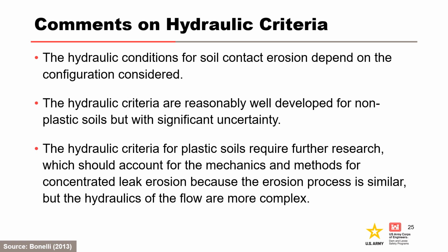So as seen on the previous slide, the hydraulic conditions for soil contact erosion depend on the configuration that's being considered. The hydraulic criteria are reasonably well developed for non-plastic soils, but have significant uncertainty. The hydraulic criteria for plastic soils requires further research, which should account for the similar nature of the erosion process to the mechanics and methods for concentrated leak erosion, but should also give due consideration to the fact that the hydraulics of the flow for soil contact erosion are more complex.